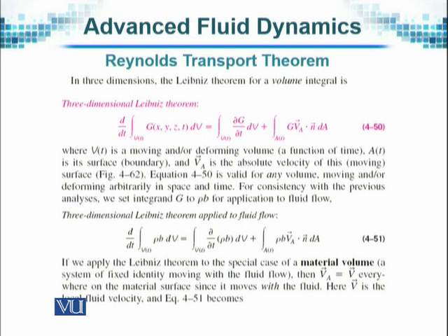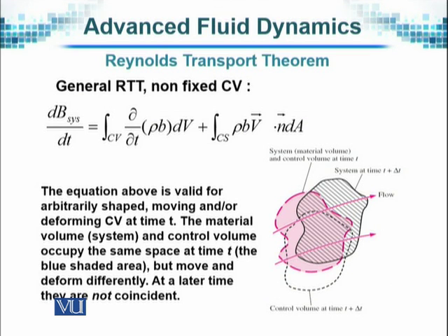Similarly, we can generalize the one-dimensional integral format of Leibniz theorem to three-dimensional form, which is given here, and the numbers here refer to the book that we are following. All this helps us in the application of Reynolds transport theorem. You will recall that I mentioned that Reynolds transport theorem provides us a smooth linkage between the Lagrangian system and the Eulerian system.